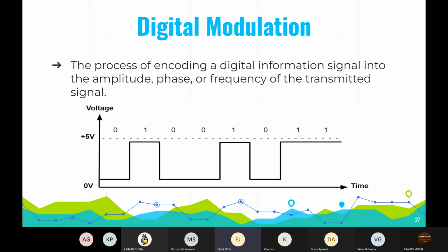So now it's time to understand what digital modulation is, and then we'll discuss why digital. Digital modulation is a special kind of modulation where the message signal is digital in nature. It may be in binary or M-ary encoded versions. In analog modulation, examples of which are FM, AM, and PM techniques that we have seen earlier, we have a sinusoidal wave carrier.